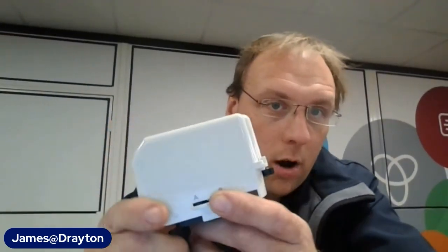And likewise, if you are going to fit a ZA6, and obviously you're not going to use the white wire, perhaps if it's just a standard S-plan system, then just make sure it goes into a dead terminal in the wiring center. Don't just snip it off, because it potentially could go live, depending on how you wire the orange and the grey. It potentially could go live when the valve is in the closed position. So just make sure that goes to a dead terminal.